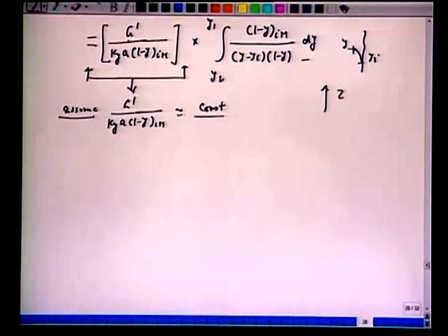Although G changes, moles per second or kg per second of the gas phase changes, and K_y also depends upon y if you recall the previous expressions, but the ratio remains more or less constant. So, this quantity has been taken out.